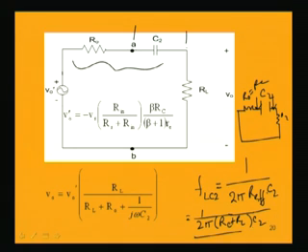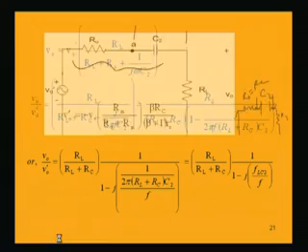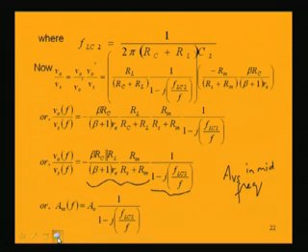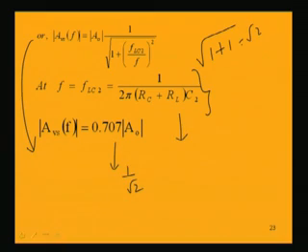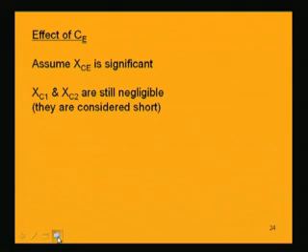So, from this I get the cutoff frequency, because this is nothing but the time constant, R into C is time constant. So, from that you get the cutoff frequency. Actually, from this whole analysis we are finally ending up in getting that frequency only, which is the frequency obtained for C2.